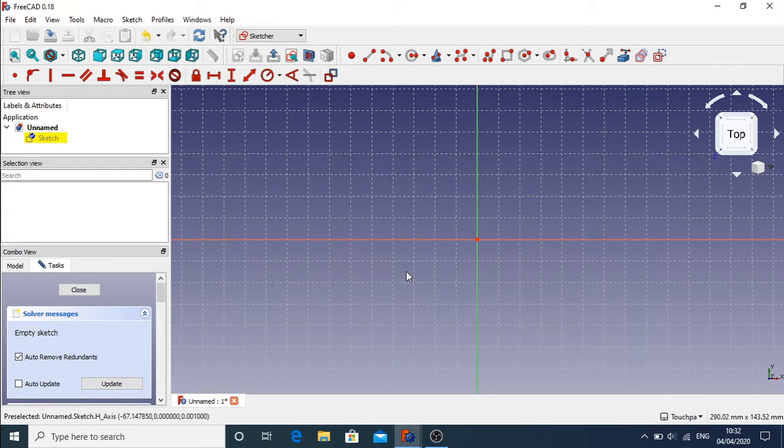So there's two types of constraint. There's a datum constraint where you actually supply some data, like a length or a width or a height. So it's where you actually supply a value for the constraint, say 200 millimeters, 300 millimeters, etc. And there's also geometric constraints, which are symmetrical, horizontal, vertical, parallel, etc. So any constraint that doesn't take data will be a geometrical constraint. So we're going to actually start with some lines, and I'm going to show you how these constraints work.